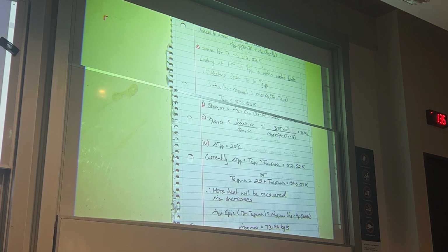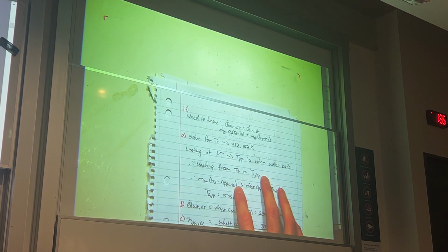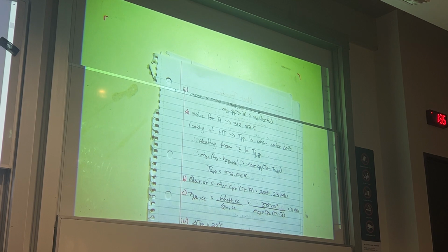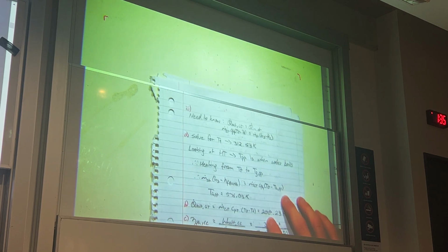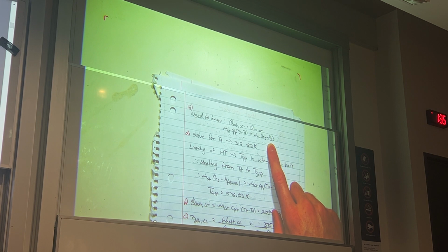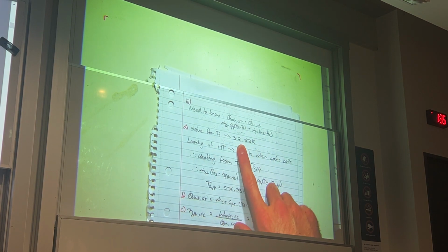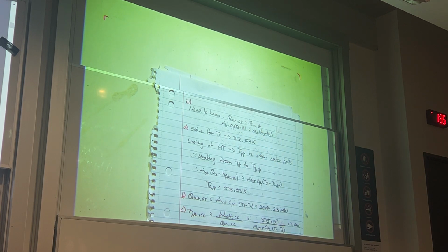So, solving for T9 is pretty straightforward. All we need to know is that the heat we reject from our gas turbine cycle goes into our Rankine cycle. So if we do the energy balances across them, we should end up with this relation. And then we can solve for T9, whether you want to rearrange or just plug in values and rearrange from there.